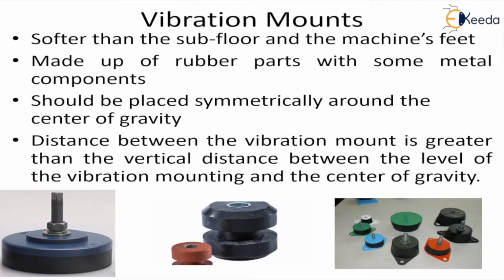If there is a vibrating machine in any part of the building, the noise can be heard in other parts also, because the vibration transmitted to the frame or support travels through long distances. So the aim is to reduce this transfer of vibrations to the supporting structure.